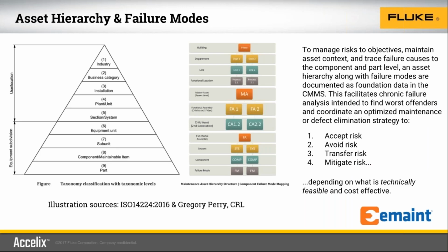So asset hierarchy and failure mode. What are we trying to do with this? We're really just trying to get down to the component level and find out the failure modes, or what are the likely failure modes. So we might perform a failure modes and effects analysis. We might perform other risk-based assessments and find out where the points of failure are. And what we're driving at here is the component level. And I'm going to go into failure modes in a moment to describe that.